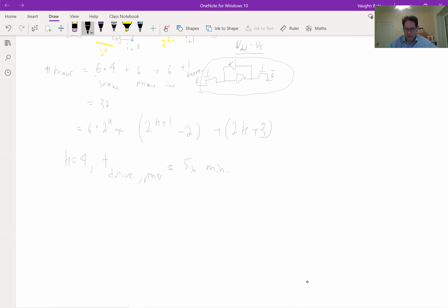If we plug those numbers in, remember, if we make a pass transistor have 5 times the minimum drive strength, then by our simple formula for area, the area of a single pass transistor would be 0.5 plus 0.5 times 5, which would be 2.5.